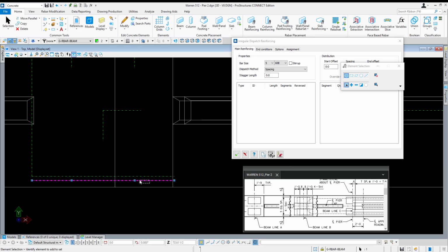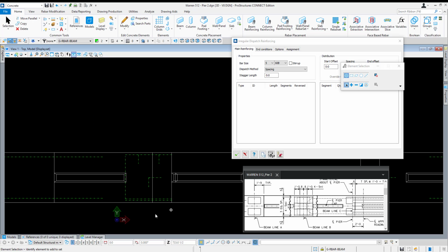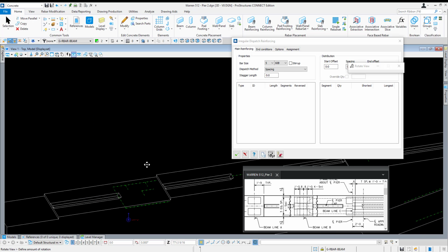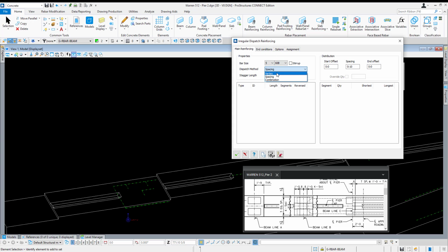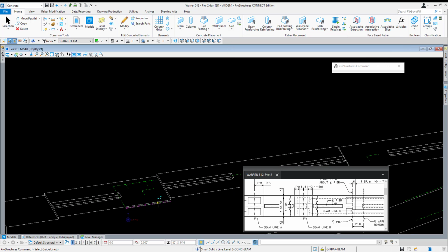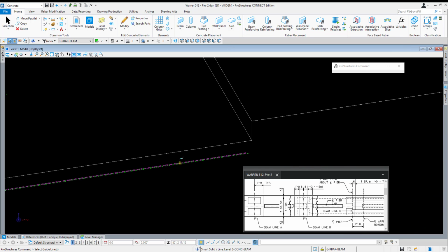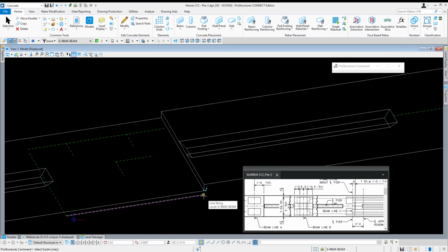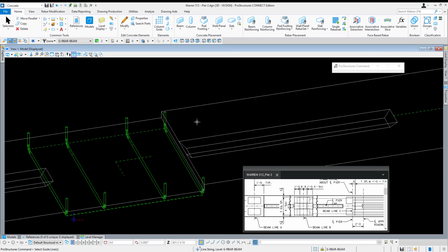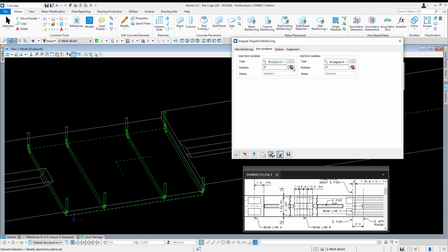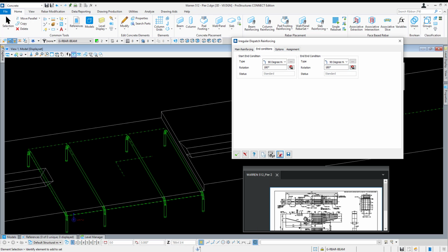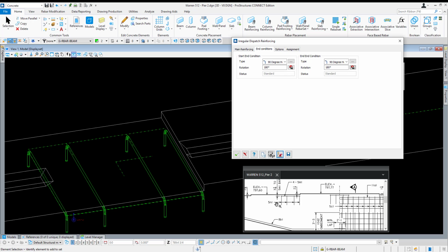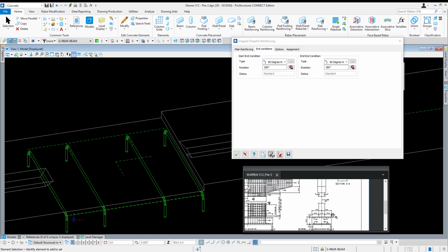And Control drag select to select the first guideline we placed and get rid of it. And now, as mentioned previously, switch back to our vertex method, select concrete, and choose our guidelines here. So line string, make sure you get the upper one. Oops, it's just a line, we don't want that. We want line string and line string. In conditions, rotate these down and modify them so that we have our 1 foot or whatever is calling for embedment.